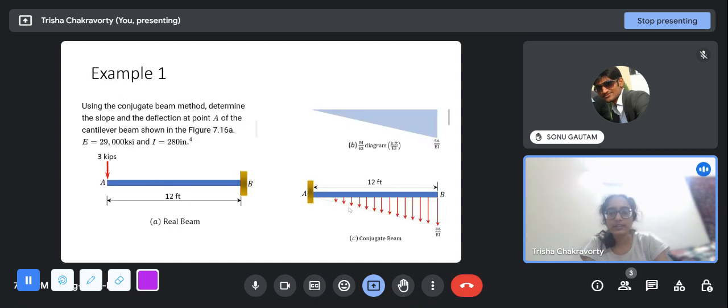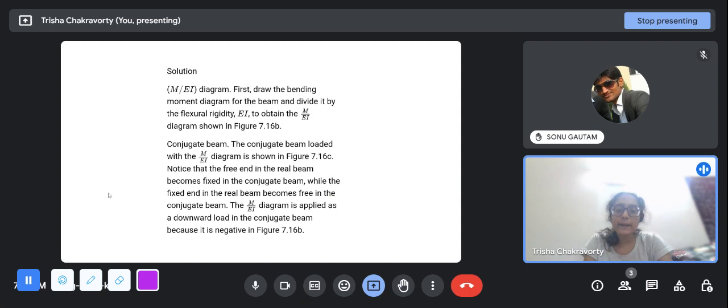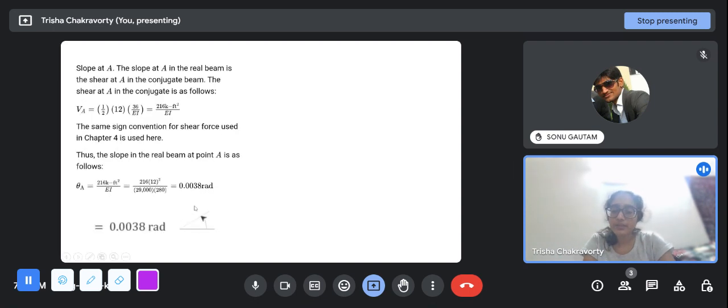And if you look at this diagram, of course you understand that if I apply a force at this tip, a point load, it will obviously deflect downwards. So the sign conventions are matching. And do keep in mind that anti-clockwise slope is positive here. It has nothing to do with the sign convention of bending moment. In bending moment, if you come from the left side, clockwise moment is positive. If you come from the right side, anti-clockwise moment is positive. But for slope, always anti-clockwise rotation is positive.